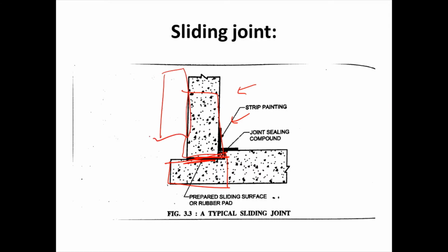And if the joint here is a rigid joint, with no sliding joint applied at the base, then the wall will not move but is bent by water pressure. But when we provide a sliding joint, your wall will be moved and this will not resist a bending moment.